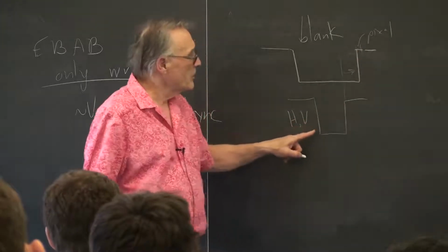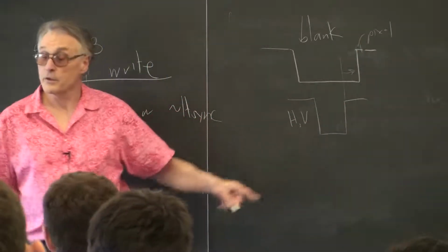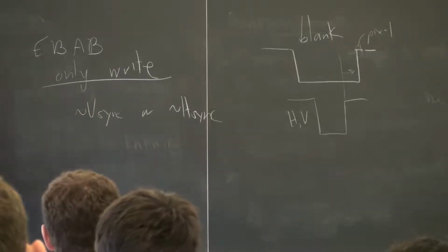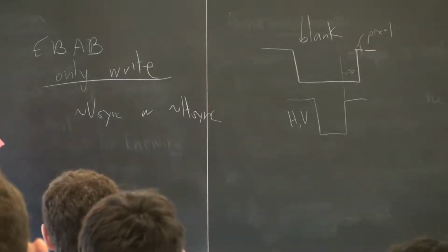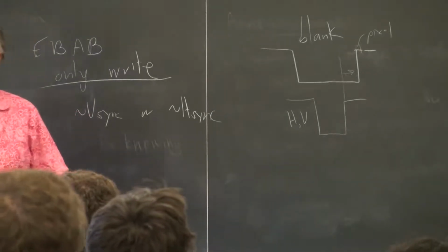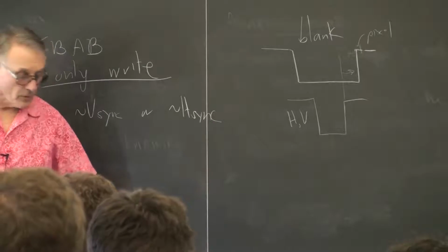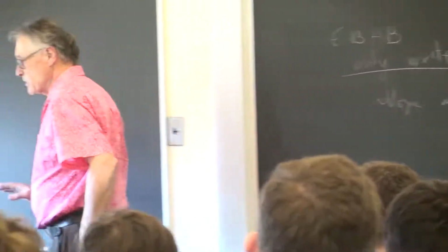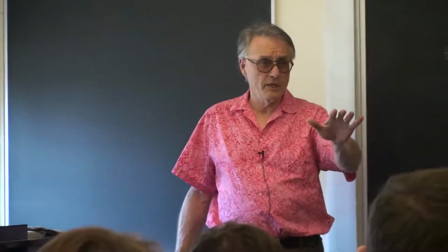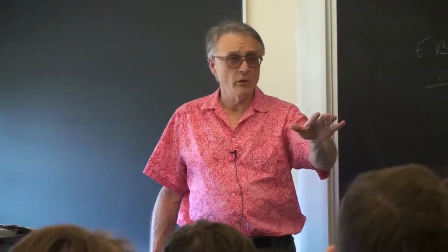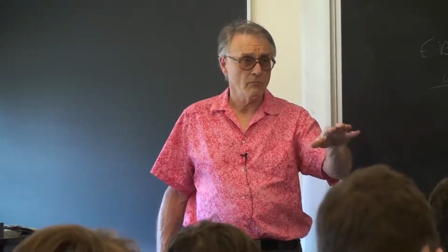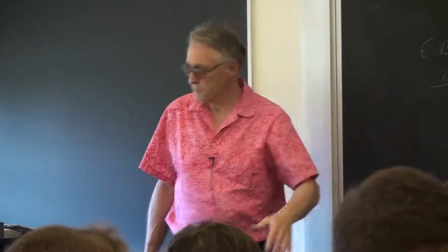So if you detect horizontal and vertical sync, you can make a system which will write to the video memory but not affect the video display. So that's one piece of the synchronization, and I think most of you saw that in the demo VGA code, right? Any question on that? You want me to show the code again or no? Yes? Okay.